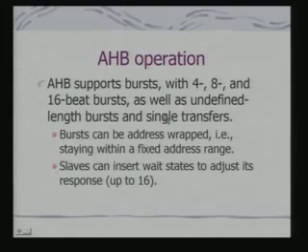It supports bursts. Bursts can be 4, 8 and even 16 word transfers at one go. And these bursts can be address wrapped. That is, the burst stays within a fixed address range, and slaves can insert wait states to adjust their response.